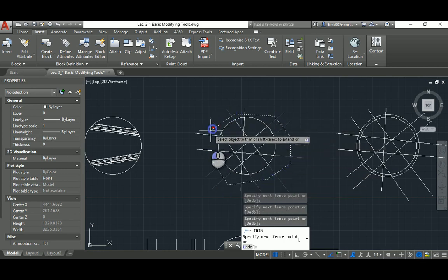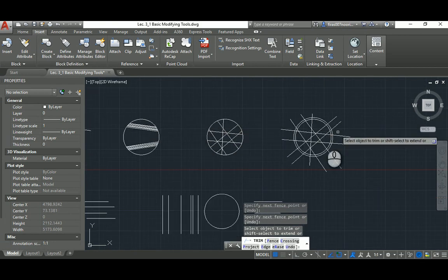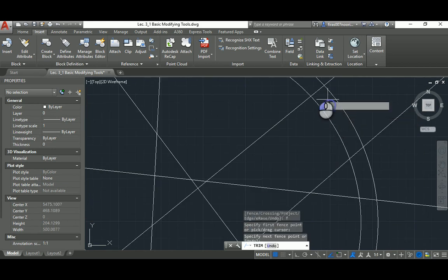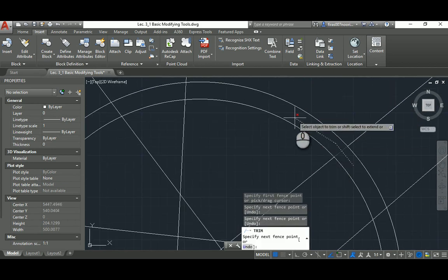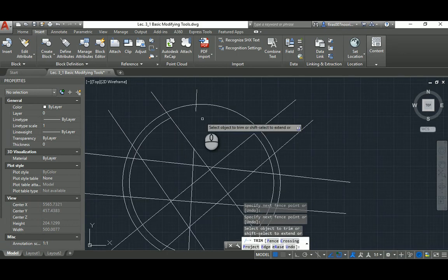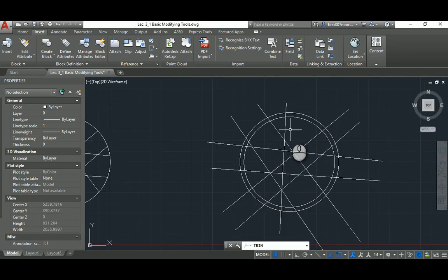And you can get a quick result out of that. Now here, if you do a fence F space, it's going to be really painful, and if you miss a little bit, you're going to mess up the whole thing. So probably that's the time where you need to use the more accurate way of using trim, which is TR1